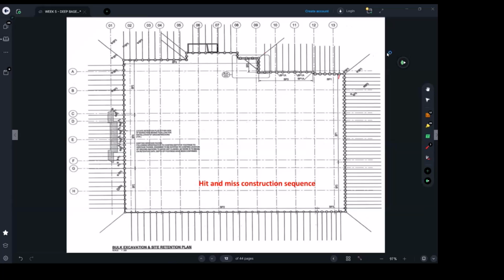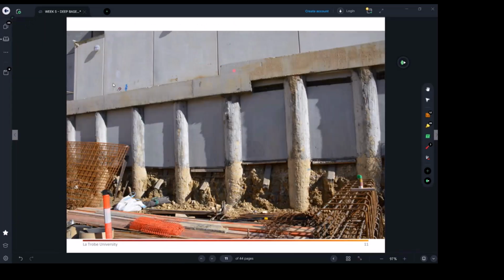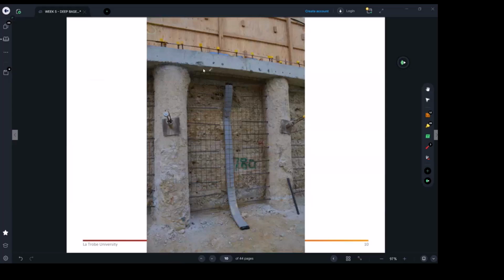All right. This is just a structural engineering plan view for, I would say, that development you've seen. You can see here these lines, and these are the piles, right? They're quite spaced very close, but maybe the scale here is too large. So these are the piles, and you can see these lines behind. They represent the nails. They are anchored. These are the anchors. These guys here.